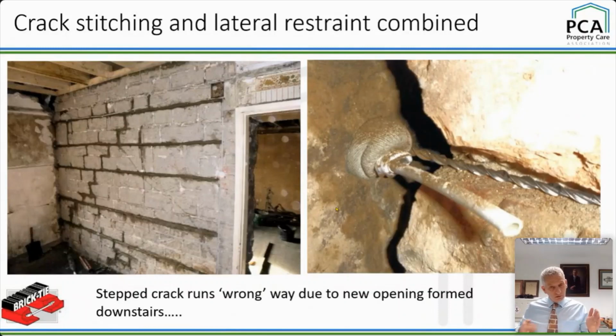On an old building, that fixing, or those fixings you put in the upstand of your strap, need to be as near to there as possible to reduce bending, but also they need to be resin bonded or grouted or mechanically fixed in somewhere to the outer leaf. I don't like mechanical fixings though into masonry.